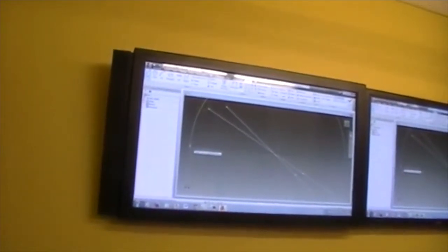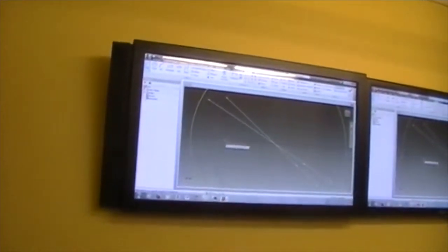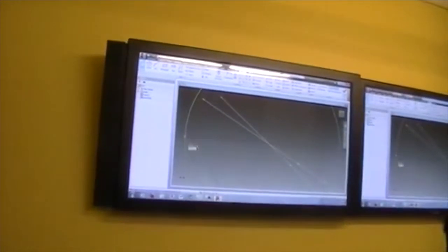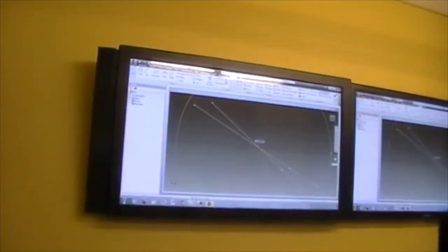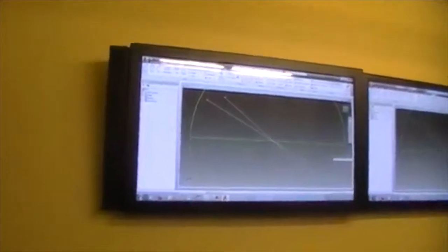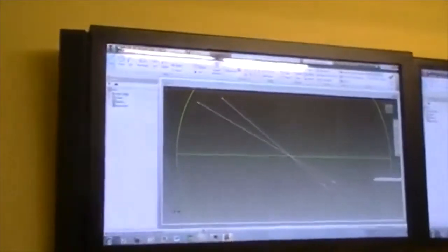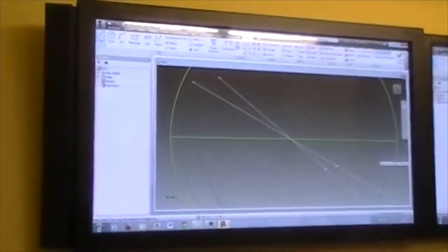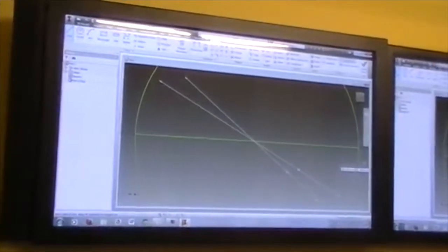So now, finally, I need to cut the bottom part of the circle off. So what we can do is draw a line connecting these two. Okay. And one thing you guys might have noticed was it was saying 64.57 millimeters. That's not clean. I mean, that just doesn't look good, and that'll get you in trouble down the road.